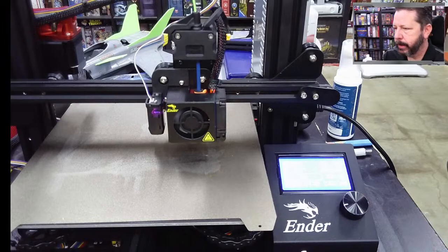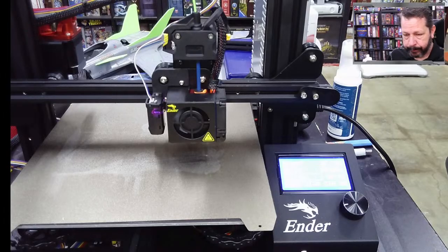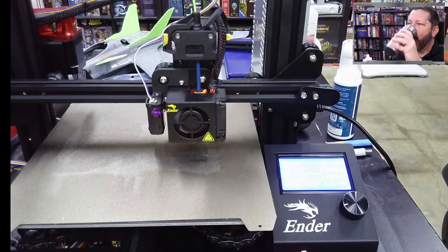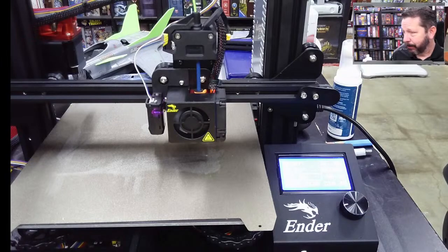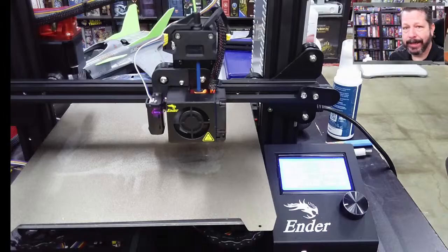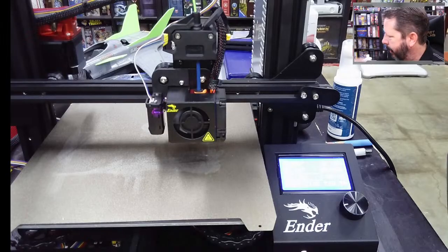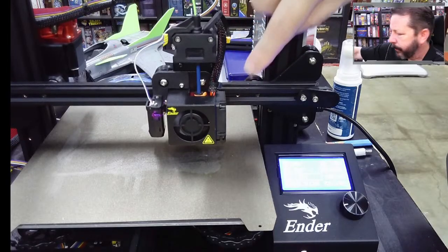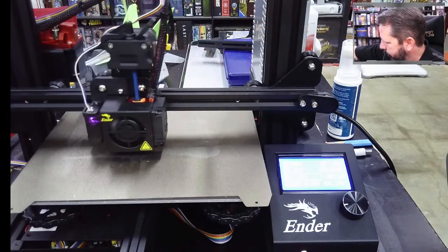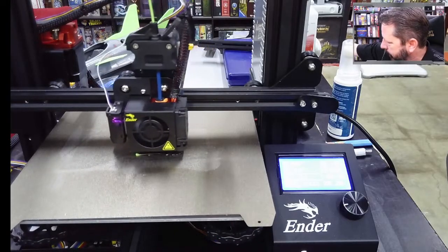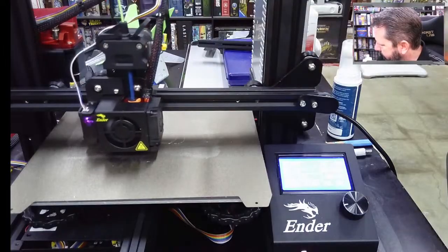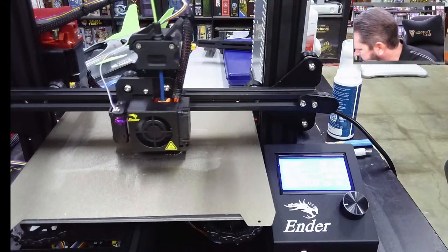Let's see where we're at over here. All right, so we're almost ready for printing. And we'll see. Again, I don't know how long it's going to take because it didn't estimate it. It probably is not going to do a purge line either. I didn't see a purge line in the little G-code generator, so we might have to help it. If you don't print with a purge line, it's just going to go straight into printing. Then sometimes I'll give it a little extra help to push some filament out to make sure that it's going to actually start printing.